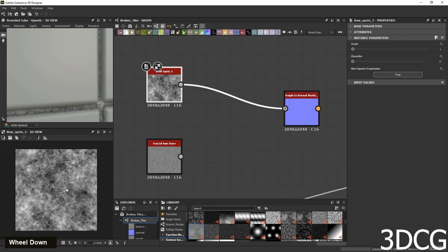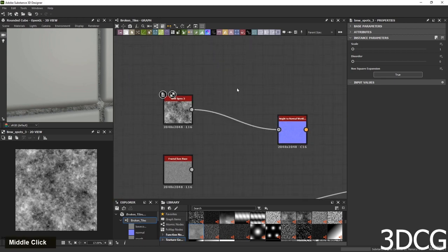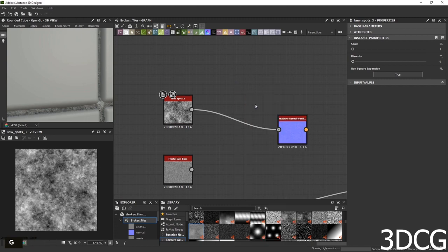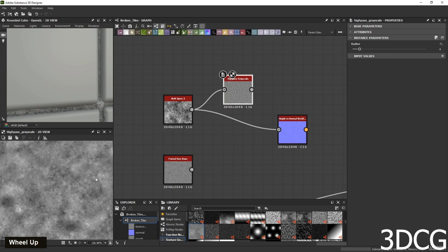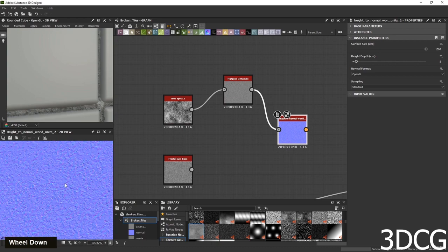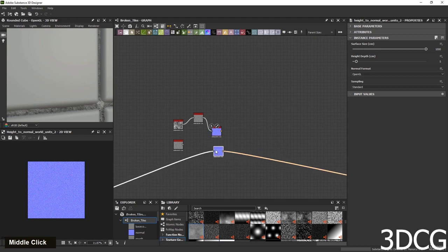If you wanted to get rid of this black and white area and normalize the whole thing, or make the average shape, you can use, where is it, high pass grayscale. Connect that to high pass and zoom really close and change the radius to make something like this. Before, after. Let's check that on height to normal value. Now we have a uniform BnW noise. Let's connect that and combine that to the original normal.